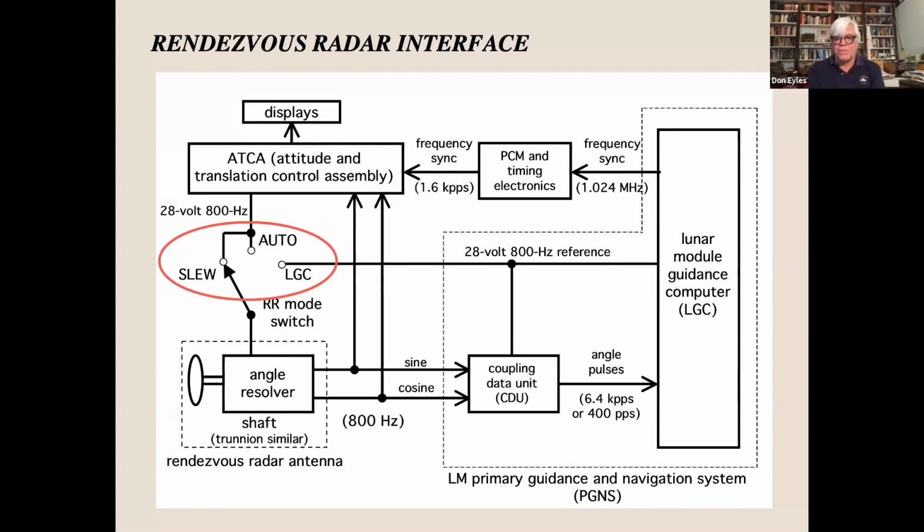And as a result, especially since, as it happened on that mission, those two reference signals were very much out of phase, enough pulses were coming to our computer to occupy about 13% of its duty cycle. That was because counting the pulses so that the software could see the position of the shaft and trunnion of the rendezvous radar antenna was done by stealing computer memory cycles, 11 microseconds each.